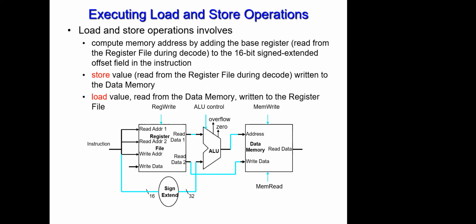One more thing I would like to highlight with the store word, I have to have this guy. Correct? Because with the store word, I have to have a physical pipe that will take the data from a particular slot in my register and copy it to the memory according to the address that is pointed to by this particular value, correct? I'm telling you, please dump this data into address 100. So I will go to 100 and then dump the data there when I have a store word, for instance. Correct? But I will not need that if I have a load word.